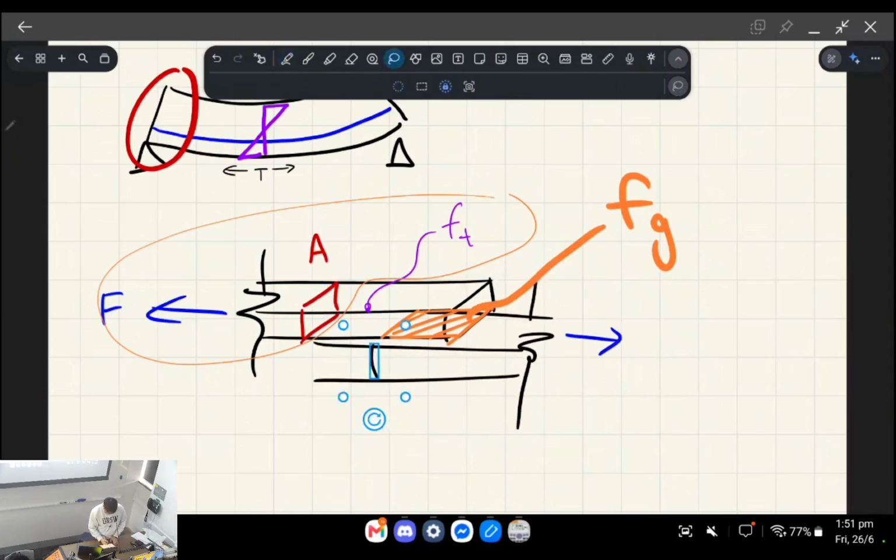So if you lap these more, you can guarantee that the glue joint doesn't come apart. And we haven't changed the cross-section of the timber or anything like that. So this is what we call a secondary design consideration. You can modify how much you lap by.